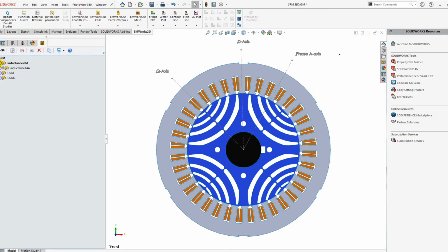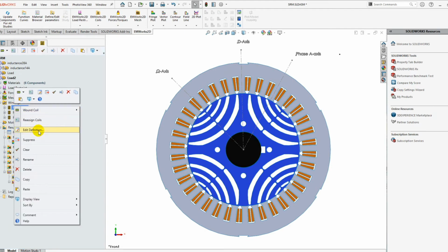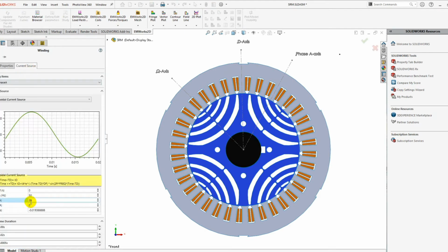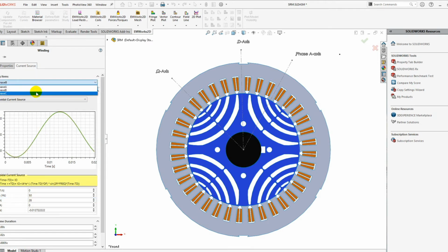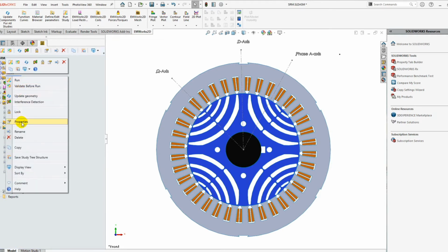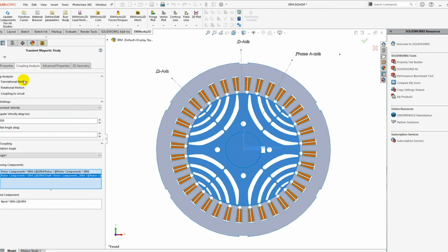Now, let us consider the load simulation using 28A sinusoidal currents for the phases A, B and C. The speed is set to 1500 RPM, which means that the supply frequency is 50 Hz.